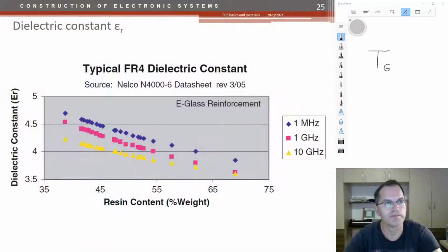This depends on the dielectric constant of the material, the permittivity factor epsilon. Your design is then made for a certain dielectric constant, and if it changes because of that and those, your antenna would go off, and this would cause problems. So it's not something that I'm just making up because I want to be smart or something. It's actually something you should be really concerned about. Okay.